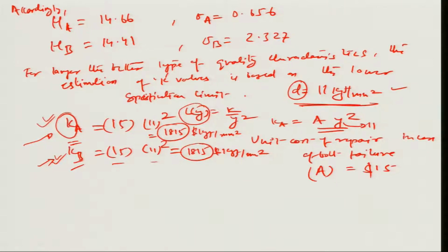Okay. So, that way it will give you a sort of bias on that vendor, that if you are not able to tightly control the ultimate tensile strength property, then it will automatically be fading away, because the D value, or the value needed for screening off the good from the bad bolts, is much higher in comparison to the other vendor. Okay.